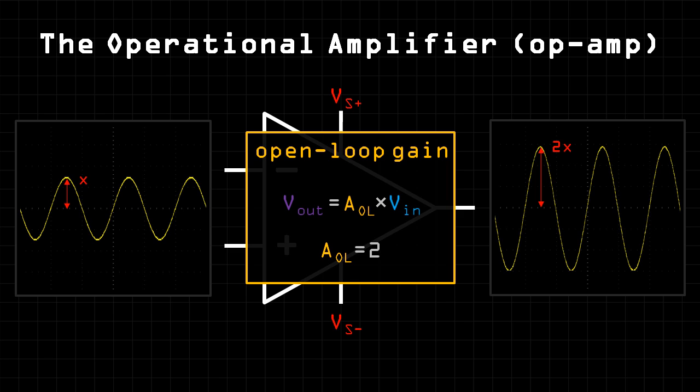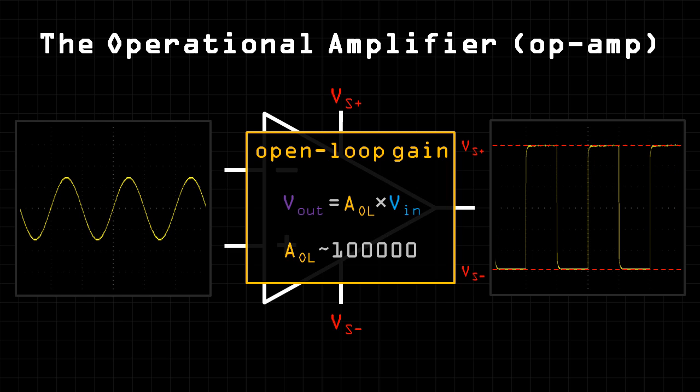One surprising feature of op-amps is that their gain is usually in the hundreds of thousands. This doesn't result in an extremely high output voltage, as the output voltage is limited to the voltage range of its power supply. Instead, this extremely high gain will cause the op-amp to become saturated at one of the two voltage rails, distorting the output. We'll see how to decrease the gain of an op-amp when we discuss negative feedback in a subsequent video.